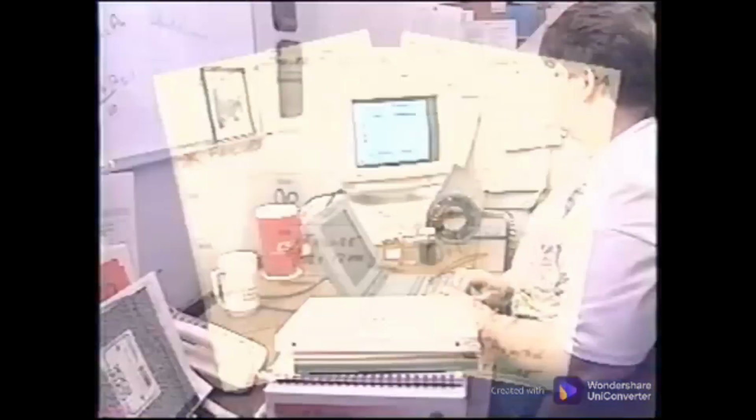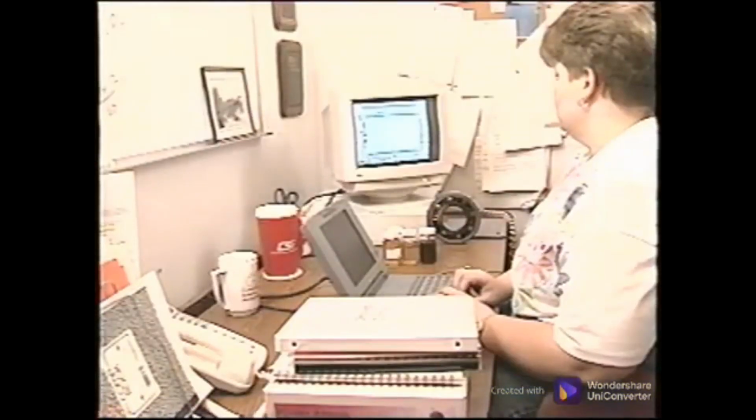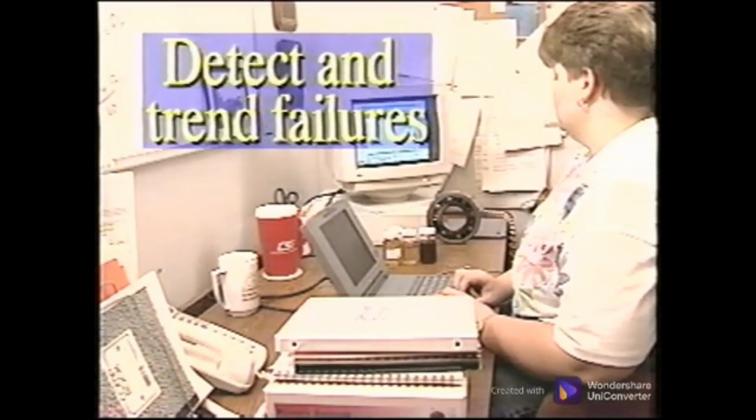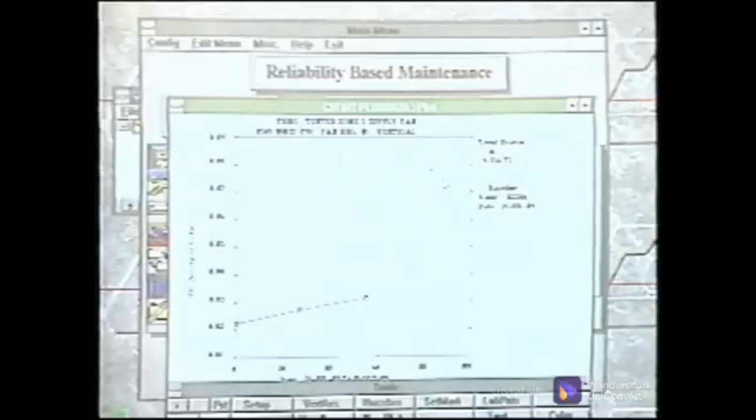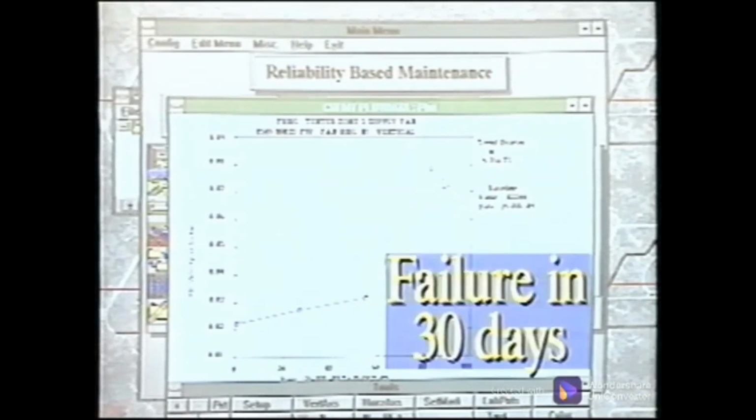And valuable information on machine condition, lube performance, and contamination is lost with each oil change. With the advent of electronics and computer-aided technology, instrumentation has been developed to detect and trend characteristics of failures, such as bearing failure, to get the most life from the machine by replacing it only when it is in progressive stages of failure. Accurately predicting the time of failure can save thousands of dollars from premature replacement of the components.